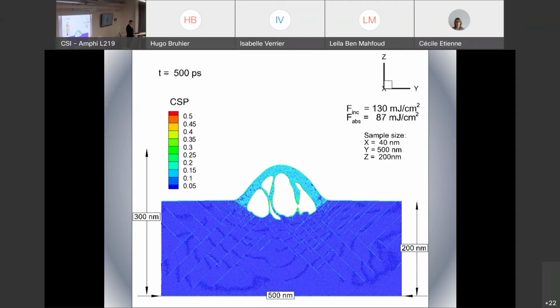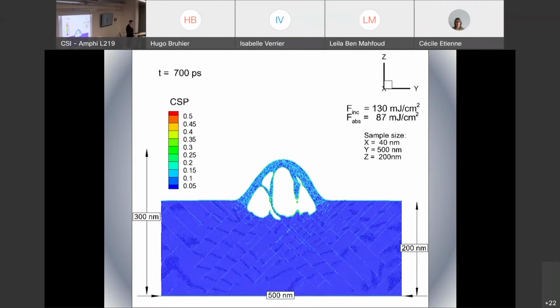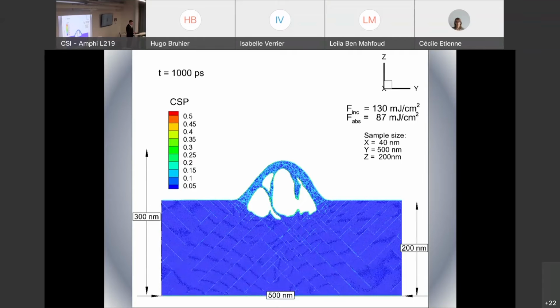And at some point you can notice formation of nuclei of new solid phase inside of liquids, so this structure is therefore already significantly undercooled by that time. And finally it solidifies, having of course polycrystalline character, because those nuclei of new solid phase have of course random orientation. So this final structure has a polycrystalline character, and it's reinforced with a number of dislocations, because formation of dislocation increases the endurance of the material.